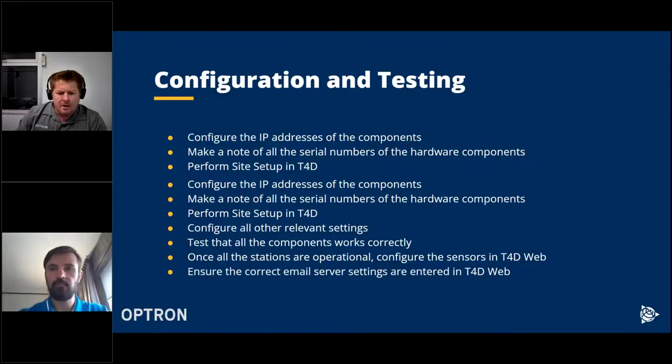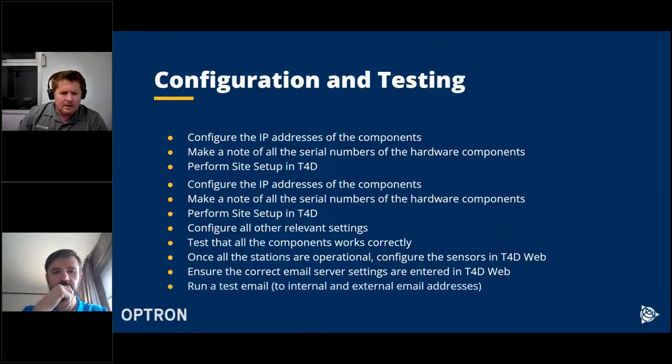Okay, then in T4D web, ensure that you have the correct email server settings for the alarming, and then run a test email in T4D web as well to internal and also external email addresses.